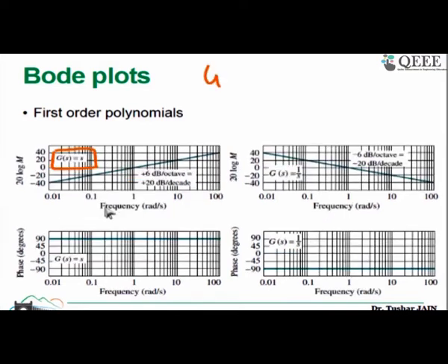There cannot be too much gap from 0.1 to 1 and the same gap from 1 to 10. No, the frequency is 1, because the plot is already in the log scale. So whatever frequency is written over here, they are the absolute values without taking any logs. But on the y-axis we have the magnitude which is written in log. We'll take these questions, whatever are there in the chat or in the question window, after we finish this basic concept of frequency response.